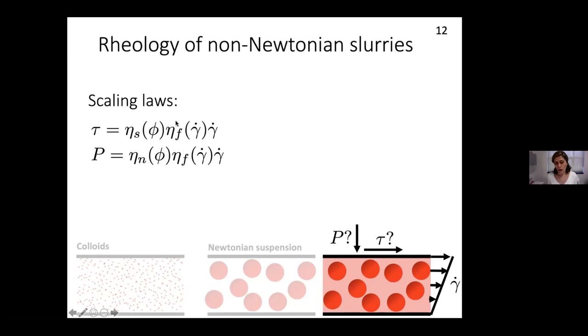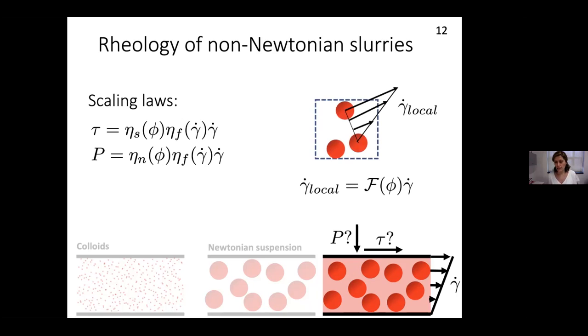We know that now, unlike the previous example where the particles were suspended in a Newtonian fluid, the background fluid is a colloid, and the viscosity of a colloid is a function of shear rate. So what shear rate? As we add these large particles into a system of liquid, particles see a local variation in the velocity that is really different from the average shear rate over a larger neighborhood.